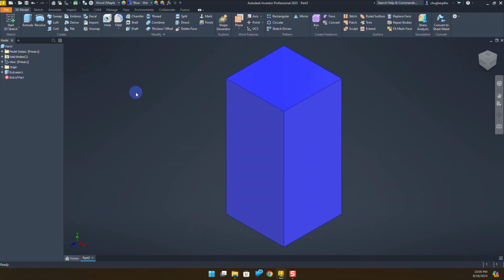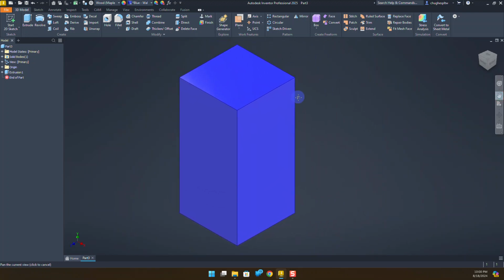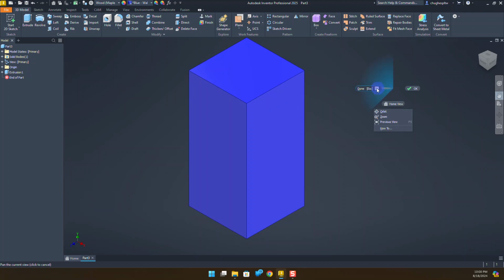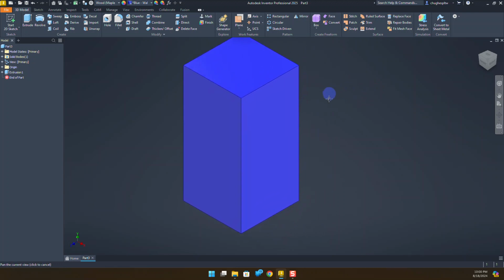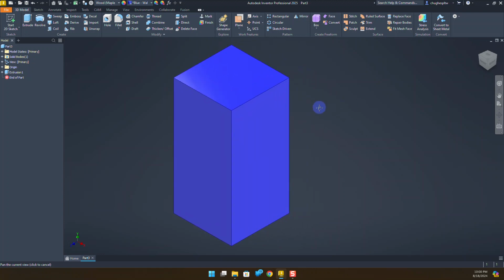As far as creating this, it was not a lot different from the cube, other than the one thing I want to point out to you, which is some of the navigation tools. So the navigation tools, you can utilize pan. Pan allows you to move across the screen like this. The other option for pan, if you're utilizing a mouse, is to press down and hold on your scroll wheel. You'll see your cursor changes to the little hand icon, and then just move your mouse around. You'll hear a click sound when that scroll wheel engages.